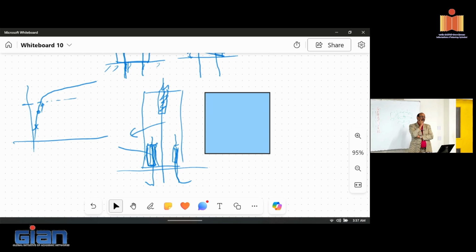Here, we go for this kind of direct connection, it's completely different. We are using the shear area, right? Now we are addressing that through pre-tension or post-tension, but still we are losing the shear area, and immediately the crack opens because it is an interface.